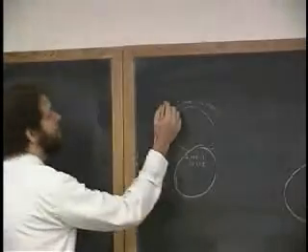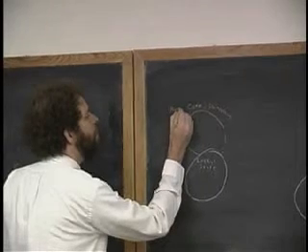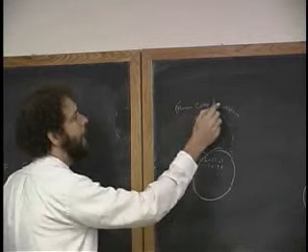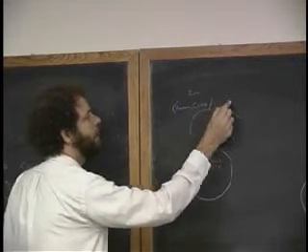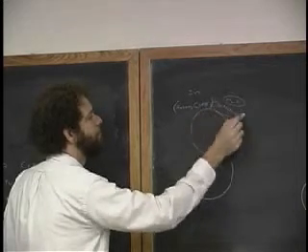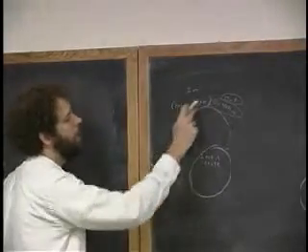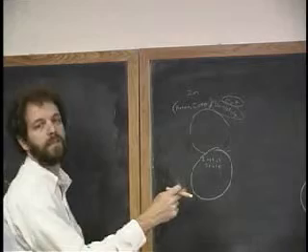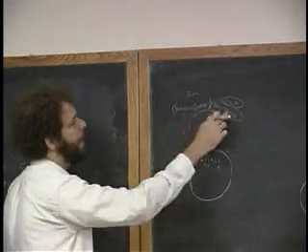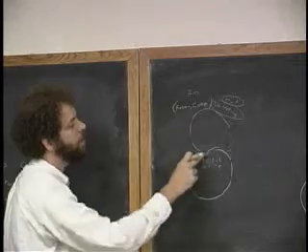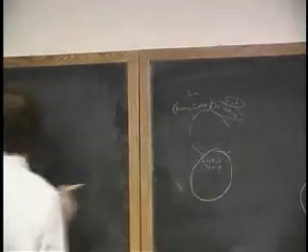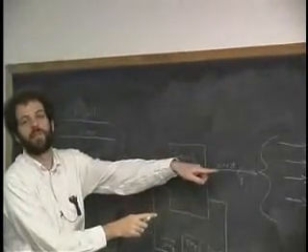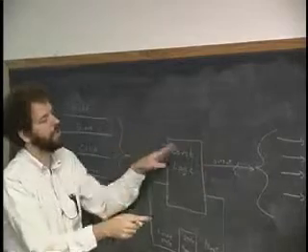And notice what I'm doing here. I am putting the input conditions here and the output conditions here. This is in, this is out. I'm also drawing an arc which says if I'm in this state and this input occurs, go back to the same state. So I'm both giving a mapping of in to out, which depends on the current state, and I'm also giving an arc which says what transition to make. In other words, given input, what should the next state be and what should the output be. And what I'm saying with that one is the output should be none of these, and the next state should be the same.